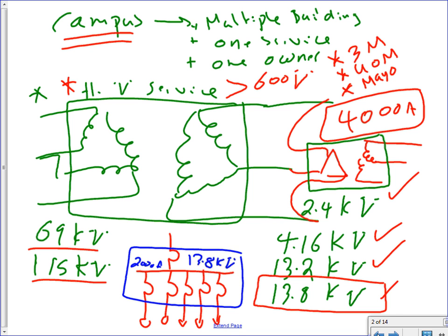Okay. We've done that. I've done that one for Mayo Clinic for a building. They brought 13.8 to the 13th floor. They have a substation on the 13th floor, and they fed everything down from the 13th floor up to the 32nd floor, I believe, or 26th floor, all the way with 480. But up to the 13th floor, you brought 13.8 to a substation inside the building. So it's big, really cool stuff inside the building. Stadiums too, I don't know how the power of the stadium works, but stadiums are a good candidate for that 13.8.